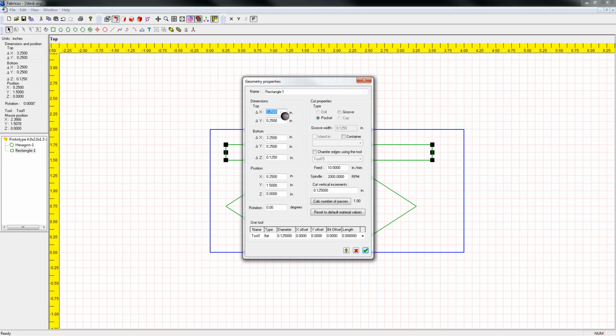So the dimensions section, we'll want to make sure that our shape, the delta Z, we'll make sure that is 0.375, which is different than what's in your binder. It would normally say 0.5, but we're using slightly thinner materials, so we'll need to modify so it doesn't cut all the way through.